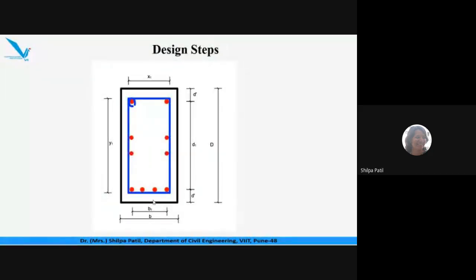That is the definition of an over reinforced beam. Whatever steel we provide on the tension side is only considered to check whether the beam is over reinforced or under reinforced. This is specifically a side reinforcement. It is not on the tension side or even on the compression side. It is along the sides. These side reinforcements are provided specially to take care of torsion. When there is no torsion on the beam, we do not provide these reinforcements. Is it clear? Yes, ma'am.